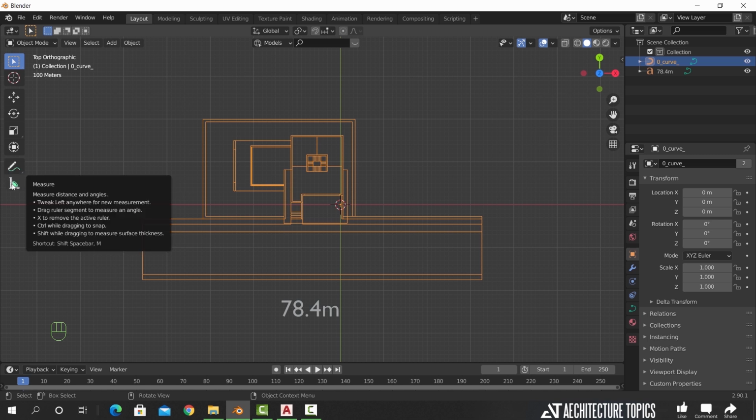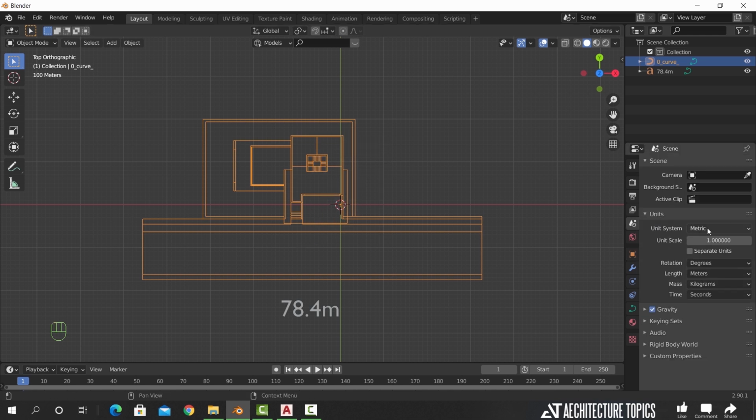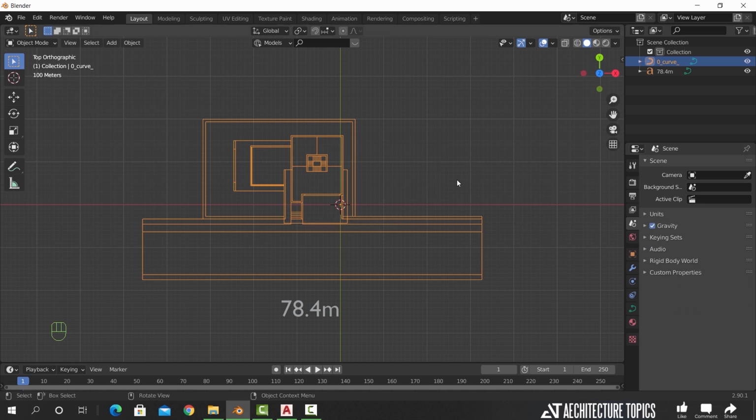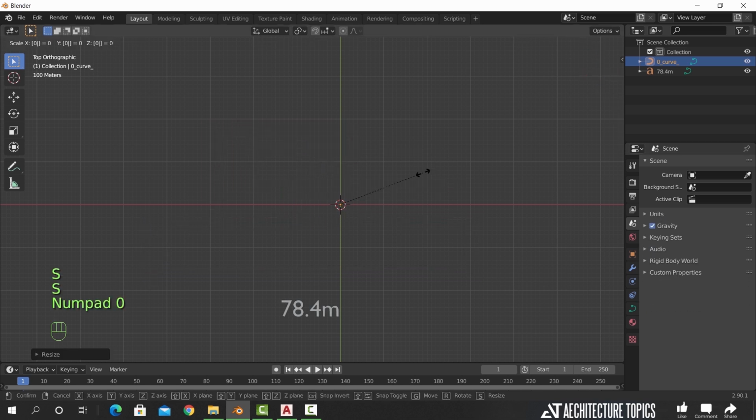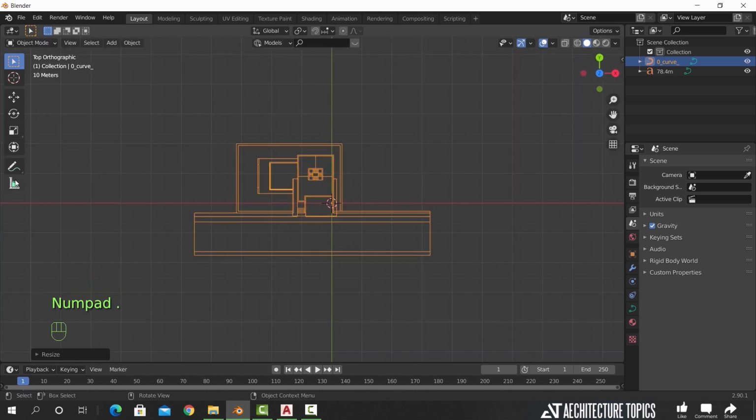We did also have this number with the drawing just to check the scale with the measurement tool. It's bigger than it's supposed to be, and that's because the CAD file is in centimeters unit, where Blender uses meter unit by default. So, you can match the unit in Blender and re-import it again, or just scale it by 0.01 and it should be fine.